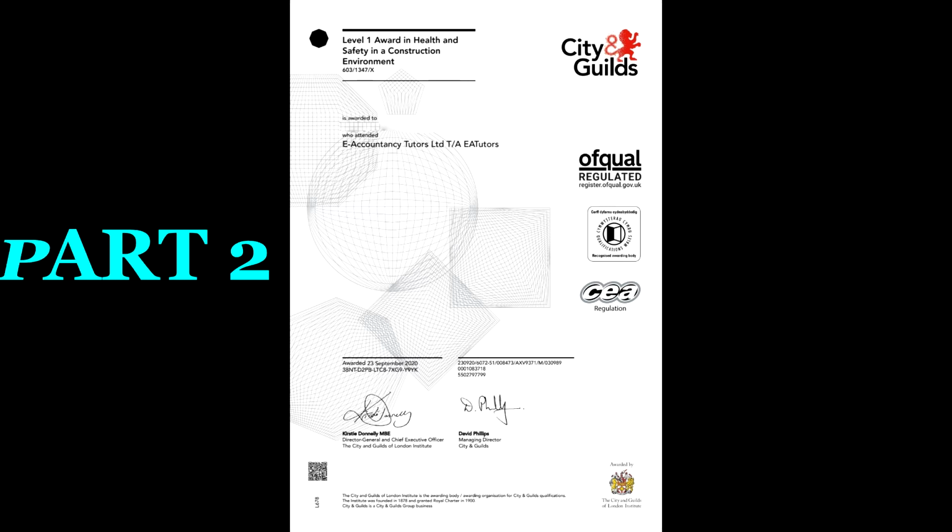And the rest of the things about ladders is a lot of common sense, quite frankly. I know it is not common, but it's common sense. I.e., weather conditions, using it on even ground. Not 2 people can be on the ladder at the same time, overreaching, too much load. The right PPE, the right boots on the ladder, 3-point contact.